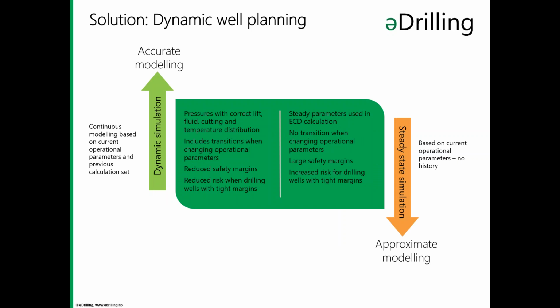First of all, one important thing is to have a good software which can do dynamic well planning. And here you can see why. When you have a dynamic simulation, there is a continuous modeling based on current operational parameters and the previous calculation set. The pressures are with correct lift, fluid, cutting, and temperature distribution. Transitions are also included when operational parameters are changing. The safety margins and the risks when drilling wells with tight margins are also reduced, and therefore it gives you accurate modeling and accurate well planning.